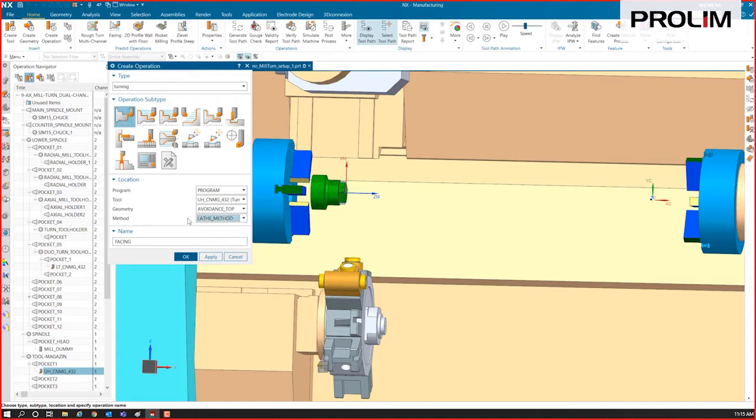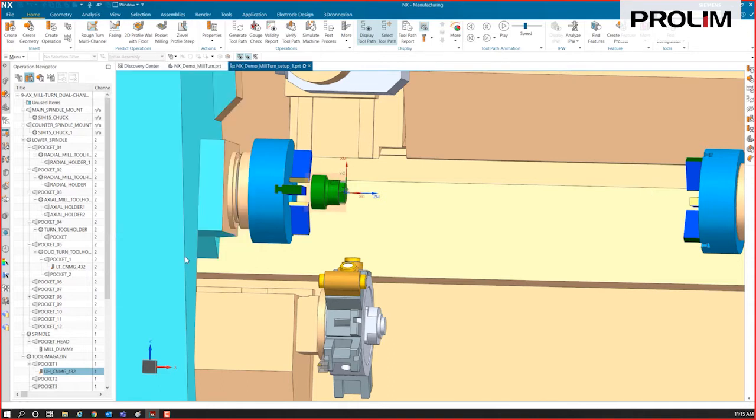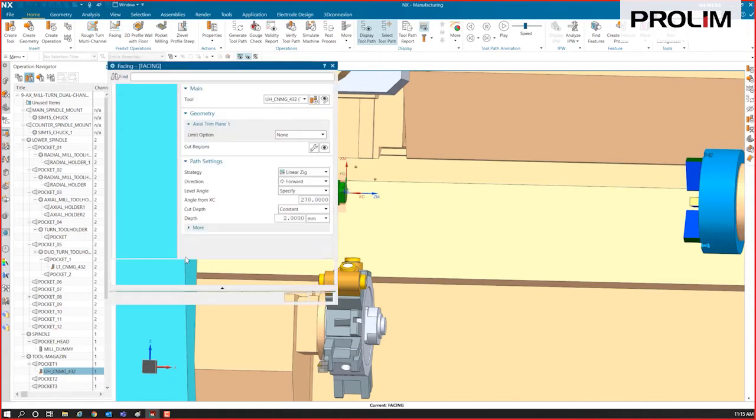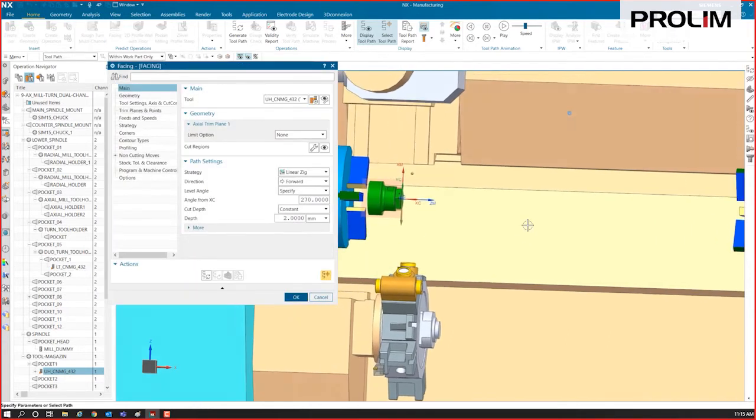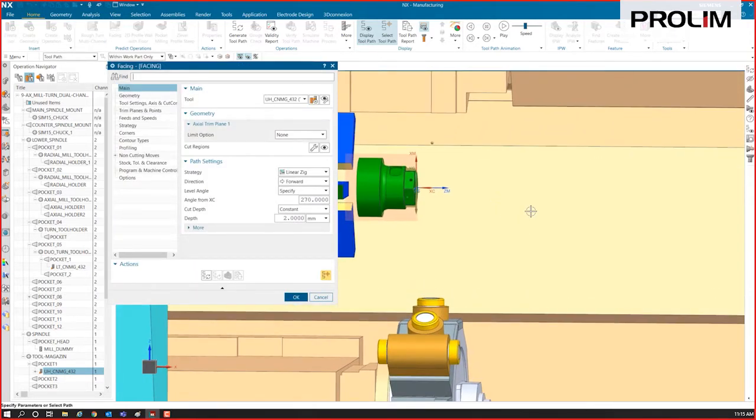So for example, this method, this lathe method, what this is telling it is it's going to leave 0 stock on the diameter and on the faces. I can create other ones to inherit information differently, and we'll do that later here in just a second. So for this operation, these Explorer dialog boxes is where we fill in our data of how we want to cut this.